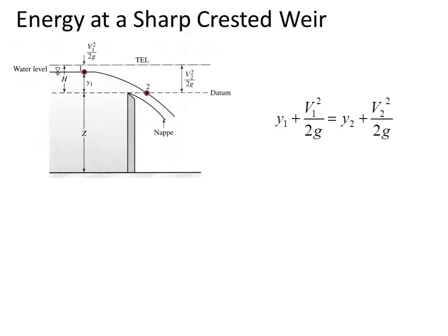It comes to a sharp crest, we could say. And the way to look at the sharp-crested weir is to compare the energy at 1 versus 2. Here we're talking about the specific energy, the energy above some common datum for the 2 points. And so there's some water surface elevation above the crest height and the velocity head. And so H in this figure means specific energy. It means the depth above the weir, and the velocity head, those two things.